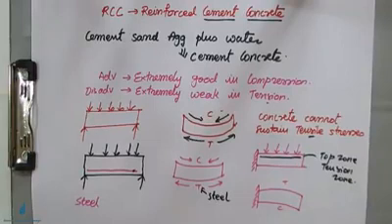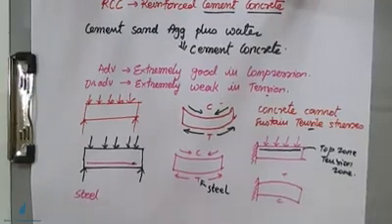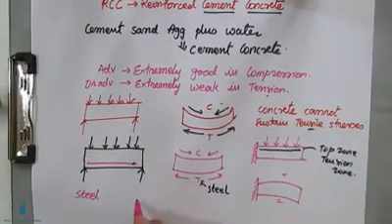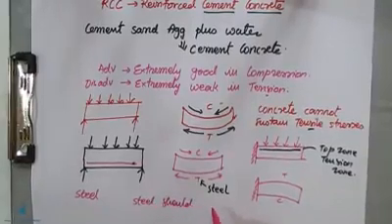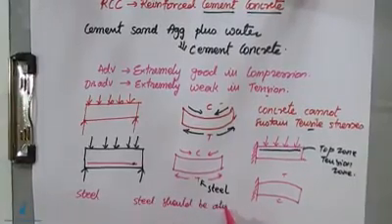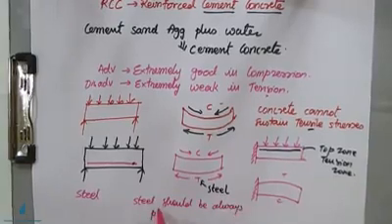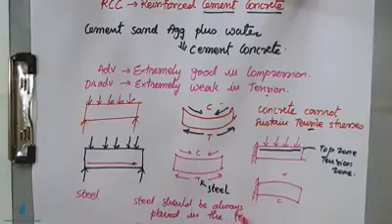So always take care that the steel should always be placed in the tension zone. Don't just remember that it should be placed at the bottom or at the top.